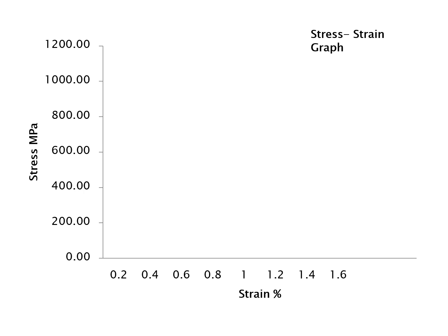This graph is called a stress-strain graph, where stress is expressed in megapascals and strain is expressed as a percentage. Let us see how this graph develops. First the material undergoes a small amount of stress, and a plot appears on this graph. Similarly, the machine keeps applying loads until the point where we get a uniform straight line. This line is a straight slope, and it expresses the modulus of elasticity. Till this point, the curve remains a straight line.